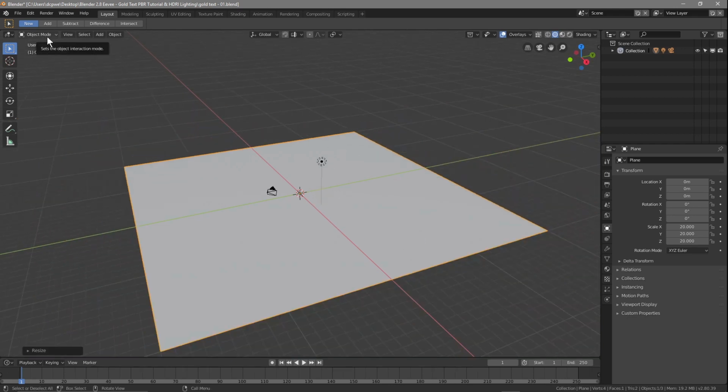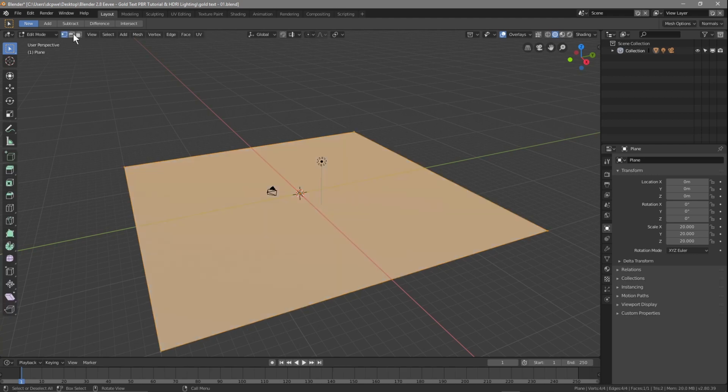We're going to go to object mode and select edit mode. And you can move between object and edit mode by hitting the tab key. One thing to note, if you've not used Blender before and this is all brand new to you, you don't know anything about 3D software, then check the link in the YouTube description where I've put a beginner's tutorial, yeah? And you might want to go through that first. So to go between object and edit mode, we can use the tab key on the keyboard. So we'll hit the tab key and we're going to do an edge select.